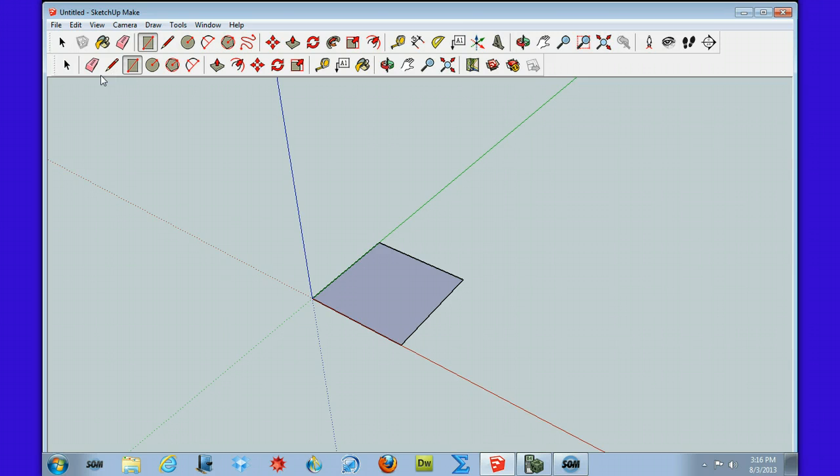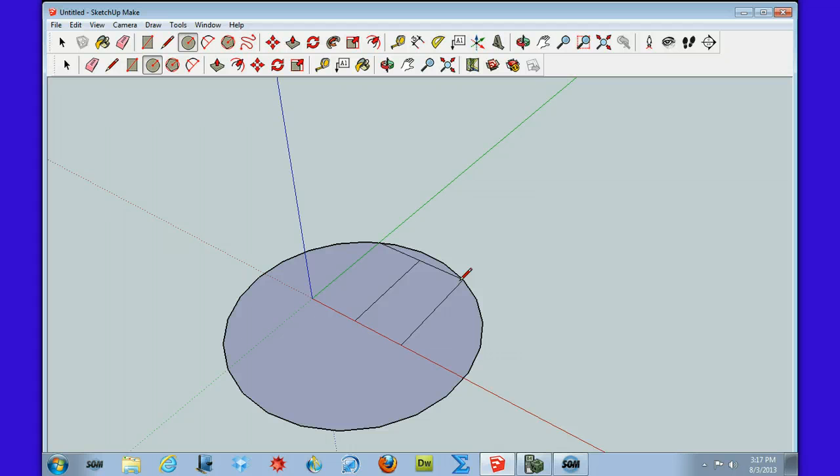Once you've constructed your square, you need to find the midpoint of the side. There's one midpoint, and I'm just going to draw this line across. I think it makes it easier to maintain and find that midpoint. We're going to then pick up the circle, and we want to construct a circle, the center of the circle at the midpoint of the square, and the radius to the diagonal, along the diagonal to the vertex of the square. So that's the circle that's going to help me with this construction.